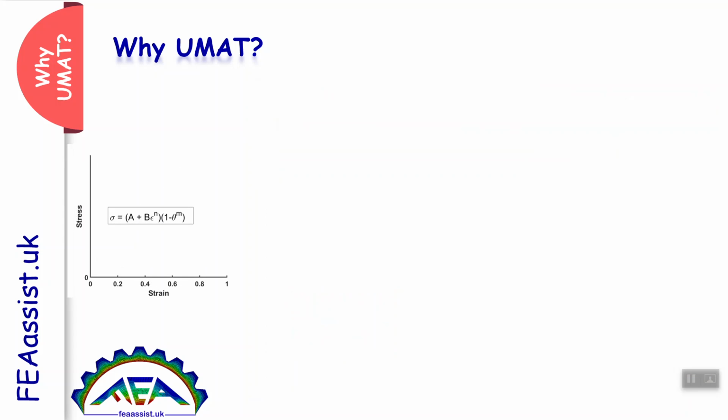If you want to solve your problem more precisely, then you need to have a constitutive equation, a constitutive behavior for your material. An equation in which the stress is a function of strain, temperature, and strain rate. In this example, we have a material that obeys this equation, which is the Johnson-Cook equation.